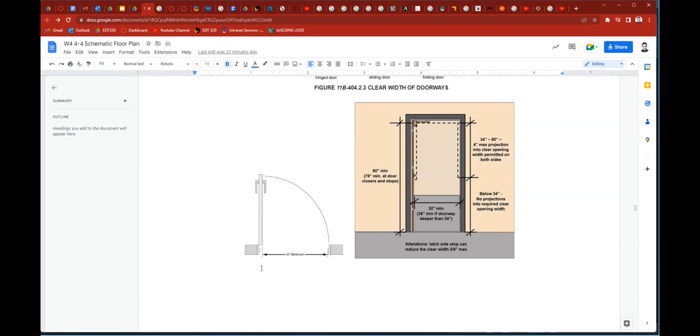So a lot of architects go with 36-inch doors. The door itself is typically 1.5 to 2 inches thick, depending on whether it's a hollow core or a metal door or whatever, 1.5, 1.75, even 2 inches, depending on what finish you want. Sometimes they put a quarter inch plywood on that door, and then they have a core of one and a half. Just to be safe, architects in offices would have a minimum door of 36 inches